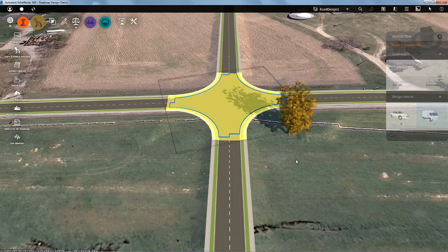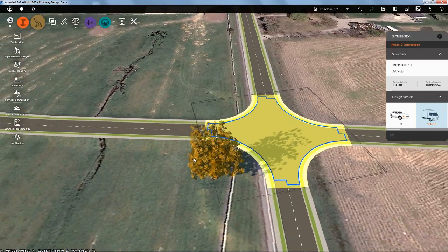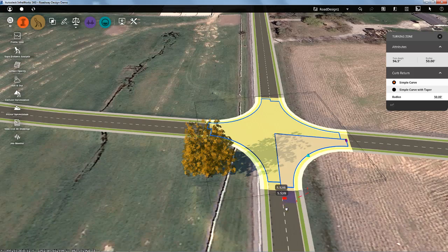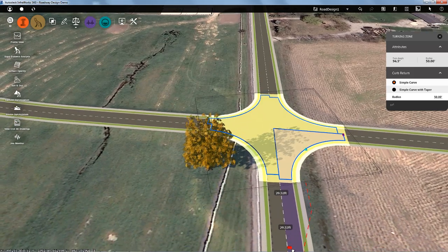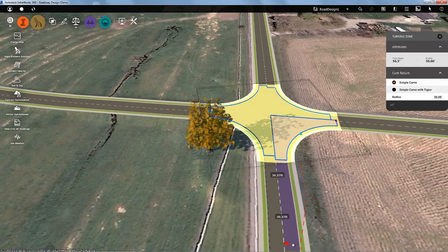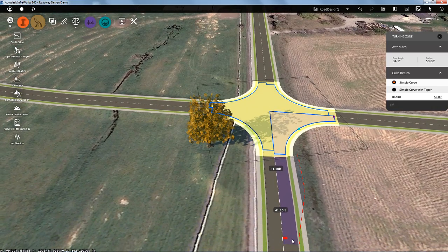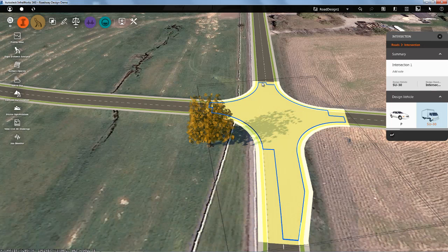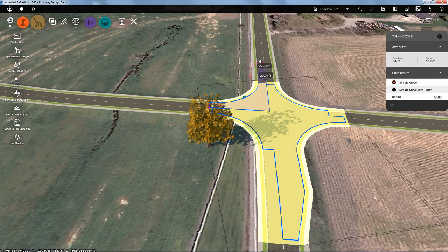Next, let's take our intersection geometry layout one step further. The primary road through the intersection will likely remain the existing north-south road. To facilitate a better flow of traffic, let's explore adding some turn lanes. To do this, we simply click on the desired lane and then drag to create our widening. For our first pass, we will see how a 40-foot distance looks. Remember, we can start with rough numbers and then use the asset card later to make them more exact once we make our final decision.